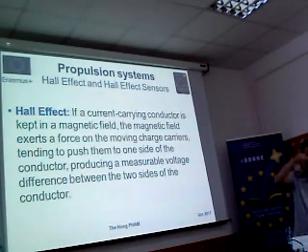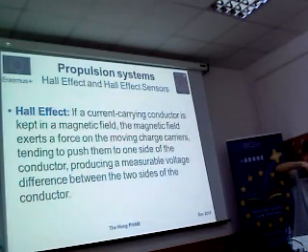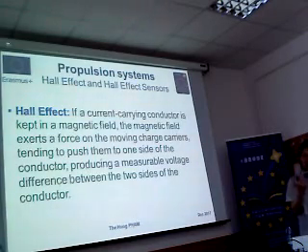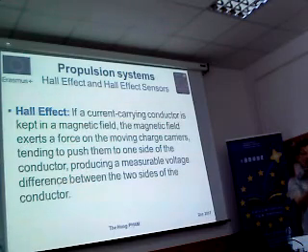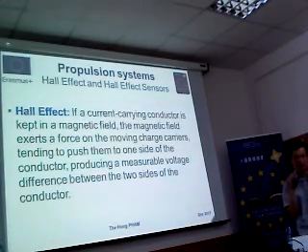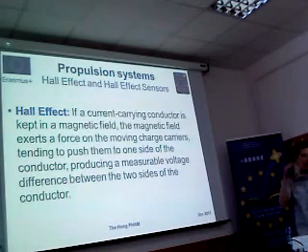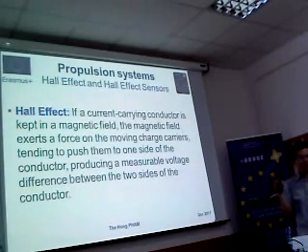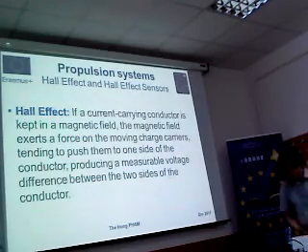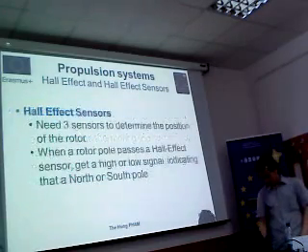This magnet will create a magnetic field, and it will divide the plus and minus into two fields. When you measure the voltage between these two, you will have some very small, maybe milli or micro voltage. Based on this, we can measure the position of the shaft of the motor in order to control it precisely. We will see it shortly.